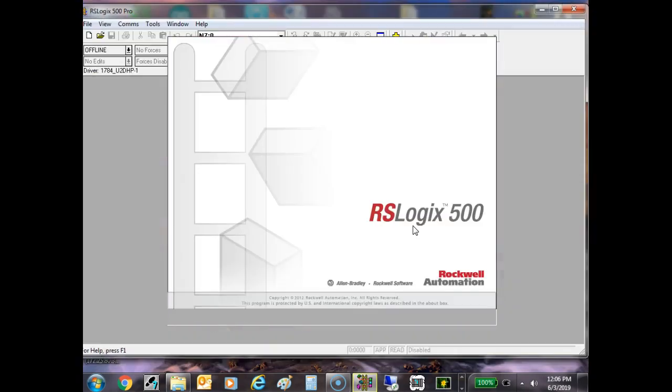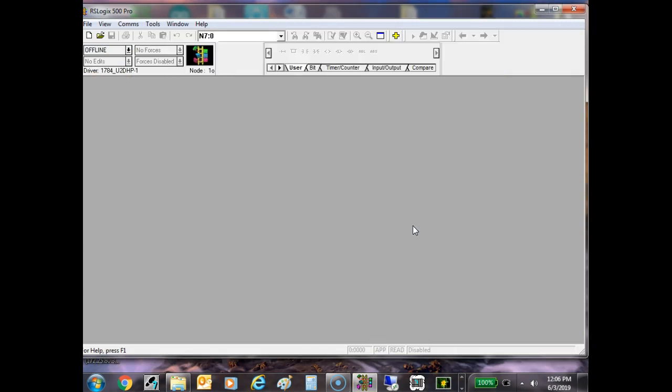So we'll show you how to do it next class. This is called forcing, and you've got to be extremely careful when you force these PLCs to assume something is a 1 or assume something is a 0. Because if you turn on an output and there's somebody out there, what you just did is defeat every safety feature that's been built into your PLC program that prevents people from getting crushed and run over. So when you force these things, you need to make sure you know exactly what you're doing.